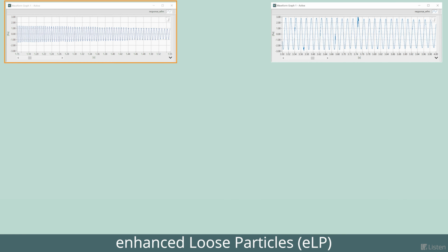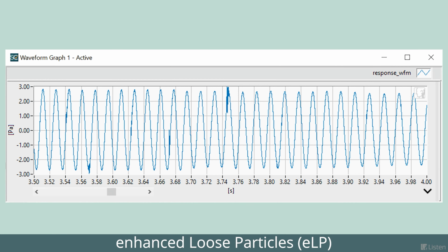This one's the good speaker. You can see a nice, smooth response waveform. And here's the speaker with transient distortion. This actually has a loose solder bead trapped inside the voice coil gap. You can see these little glitches on the waveform. That's the rattling solder bead.